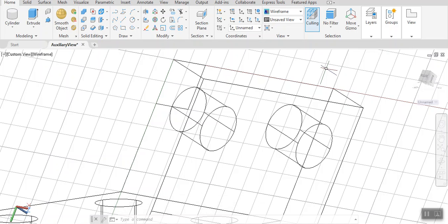However, now it's kind of sticky situation because the third hole is supposed to be perfectly in the middle and only 1 inch below the first one. So distance between two holes is 3 inches. That means this next hole is going to be 1 inch below this line, the first hole, and 1.5 inch to the right.